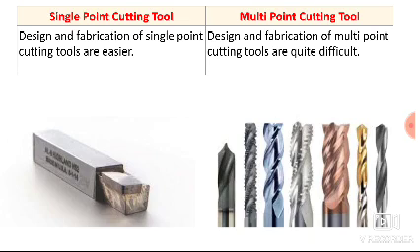Now the next difference is, the design and fabrication of a single point cutting tool are easier, and the design and fabrication of multi-point cutting tools are quite different. Here I am showing the single point cutting tool as well as the multi-point cutting tool. Here you can see the construction of the single point cutting tool is very simple. You can easily fabricate it. Whereas if you carefully look at the images of the multi-point cutting tool, its shape is very complex. So the design as well as fabrication of a multi-point cutting tool is quite difficult, and that becomes clear with the help of these two images.